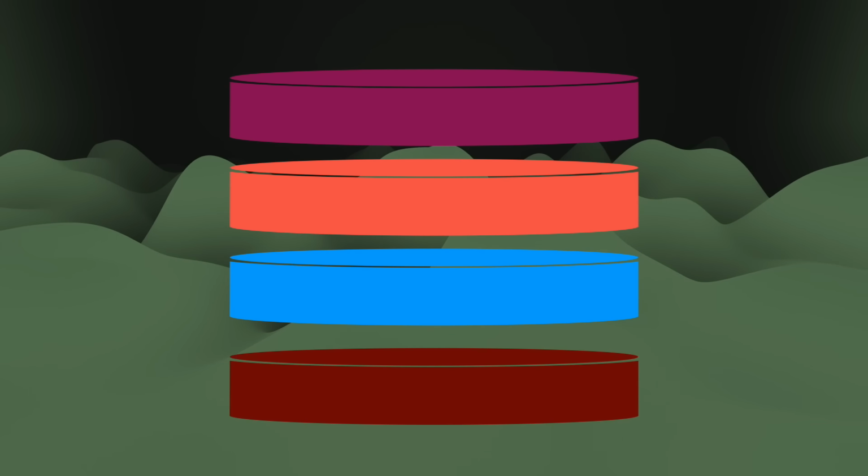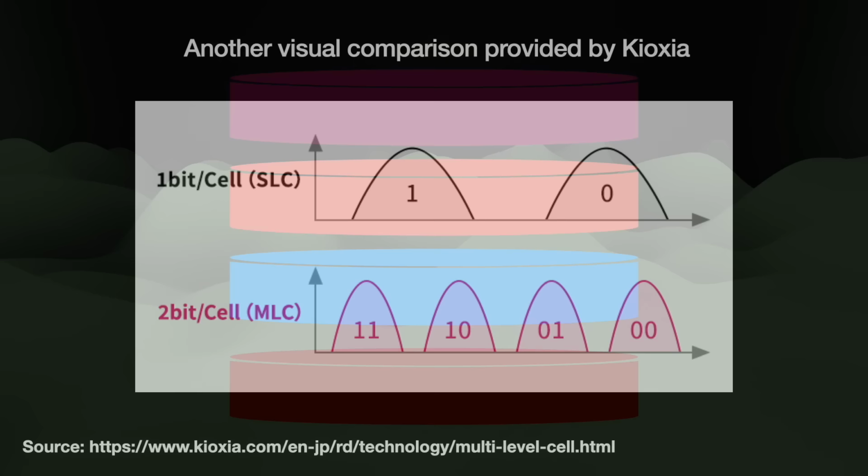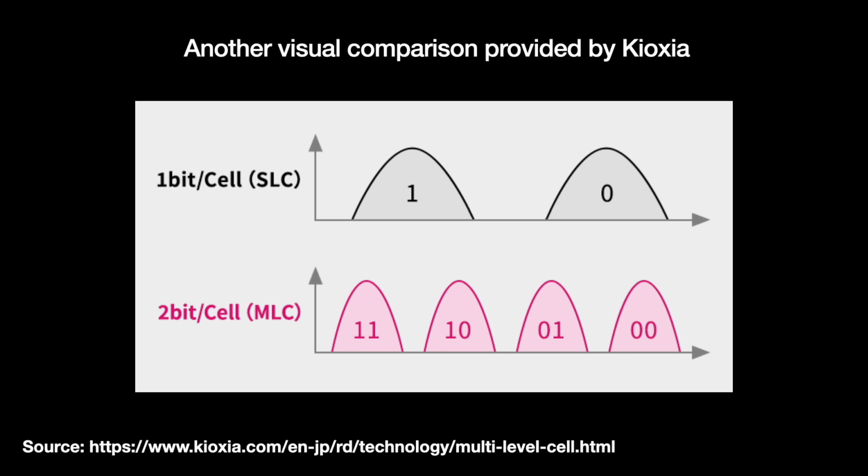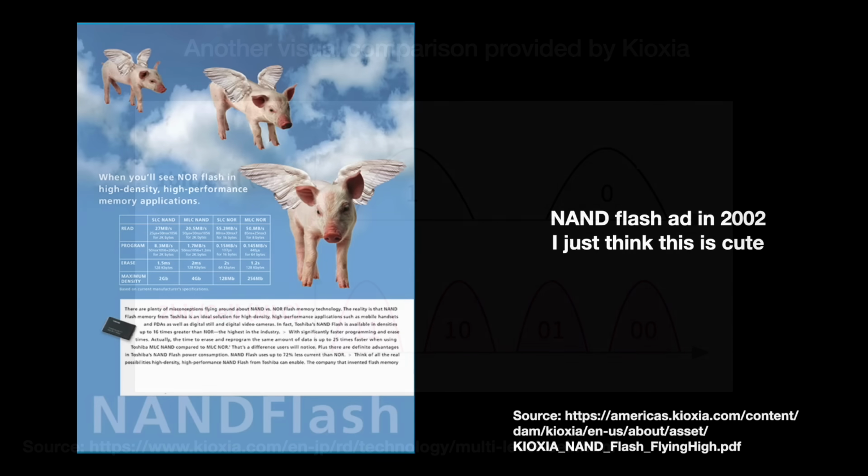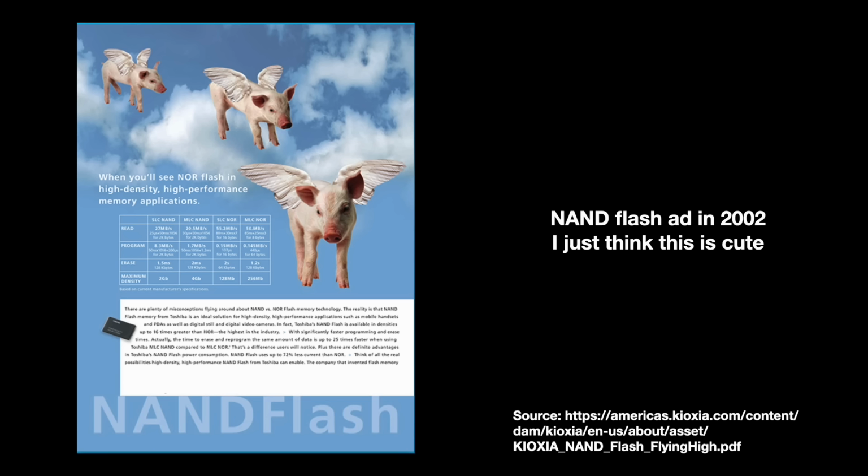Creating more of these voltage steps adds capacity to each cell, but at a cost. Imagine the bucket being divided so many times that it starts getting difficult to measure where the sand level is at. It was hard to do this consistently, requiring a great deal of precision in both writing and reading. One tactic has been to give the chip more time to quote-unquote settle, reducing noise. So these multi-level cells pull data out of their system more slowly than their earlier cohorts.